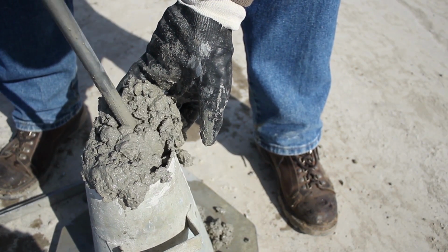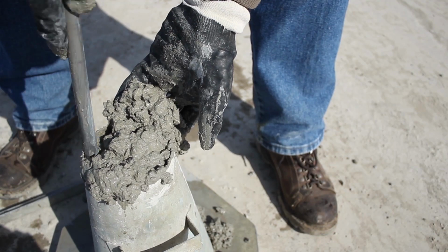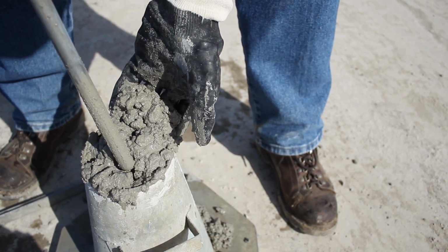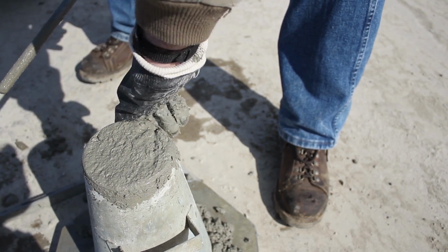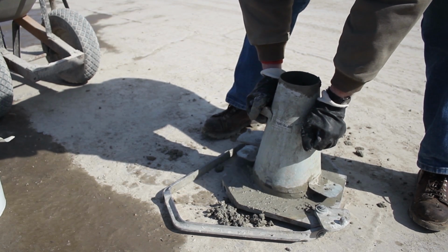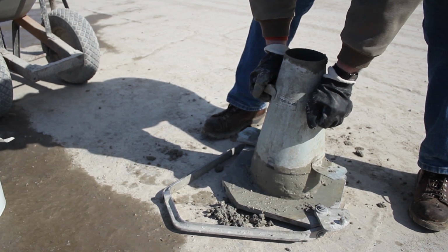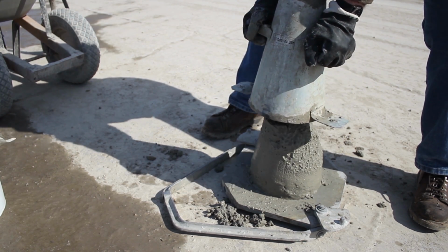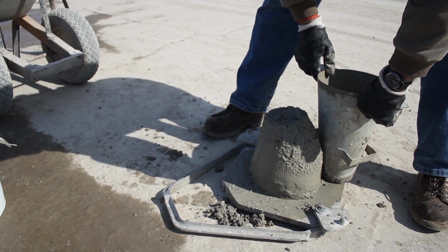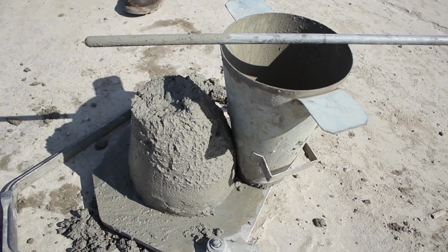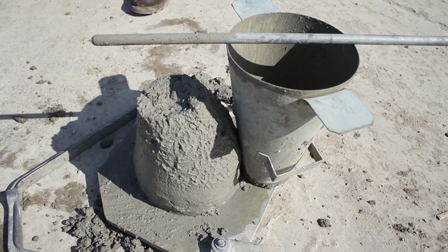Concrete mix designs have a little wiggle room figured into them so that if some extra water is added to increase the workability, it won't compromise the final strength of the concrete. However, adding excess water can reduce the strength of the concrete, causing it to set very slowly, crack, and ultimately fail. As a mixer driver, it is your responsibility to make sure the concrete is the slump the customer requested when it arrives on the job.